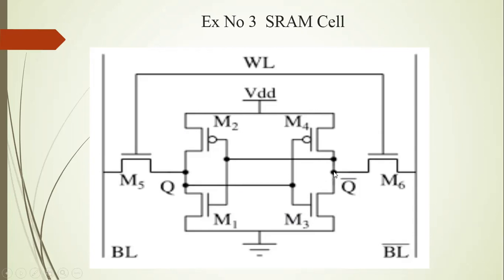After that, you get this logic data out through these N channel MOSFETs. The N channel MOSFET gate input is logic 1, so it passes this logic 1 from this place to this place. After that you connect one inverter here, and then you get the inverted output at another location. So this is the working of the SRAM cell.